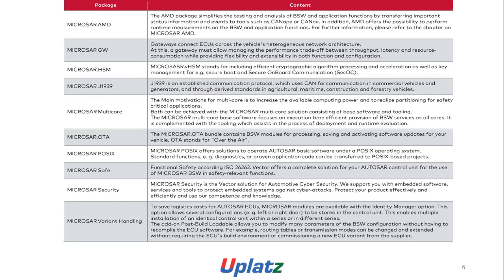MICROSAR GW. Gateways connect ECUs across the vehicle's heterogeneous network architecture. Here, the gateway must allow managing the performance trade-off between throughput, latency, and resource consumption while providing flexibility and extensibility in both function and configuration.